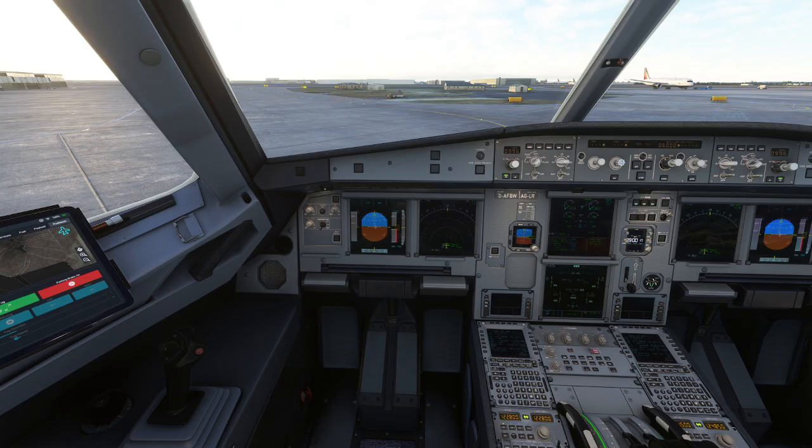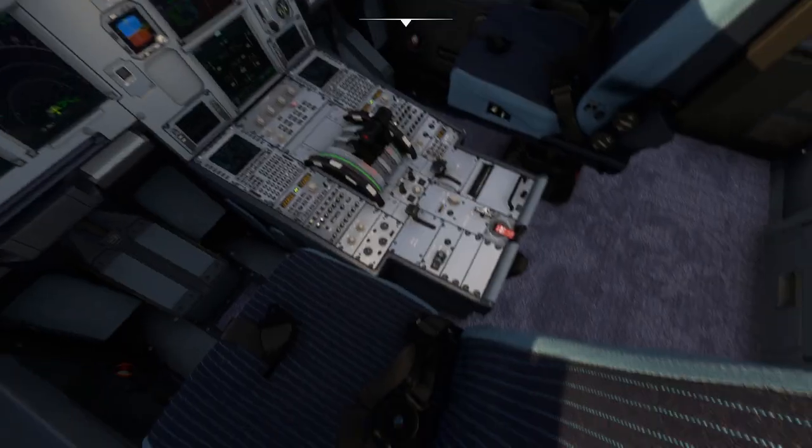Seabird 41 Romeo, continue Alpha, stand 515. Continue on Alpha, stand 515. Engine startup checklist is completed. APU, APU bleed, APU gen is okay. Thrust reverse in idle. Parking brake is on.